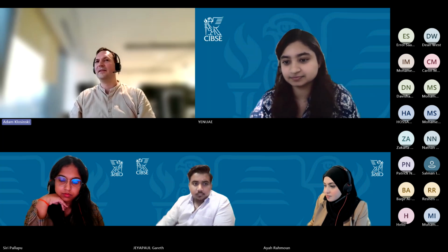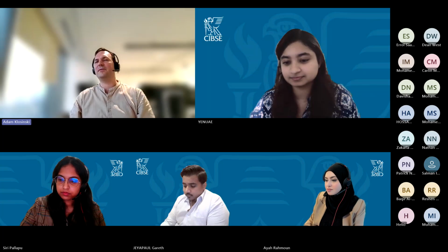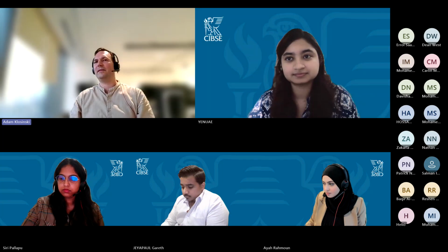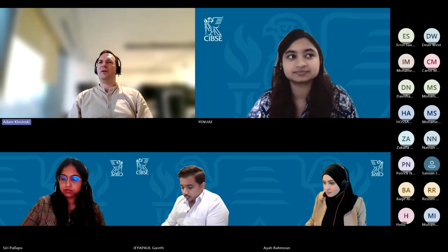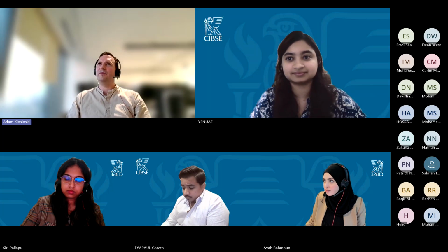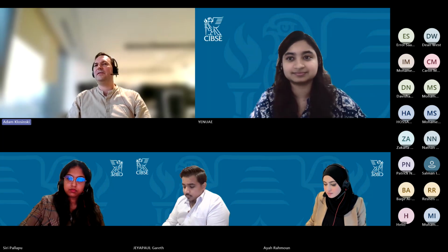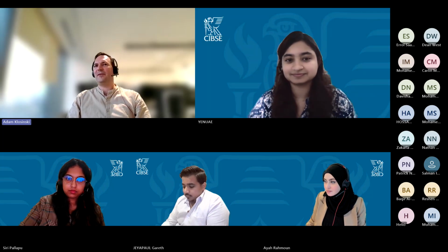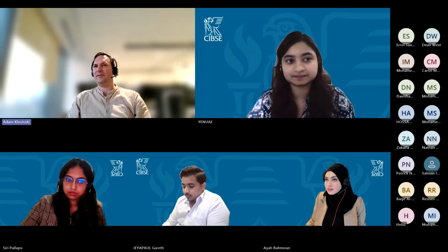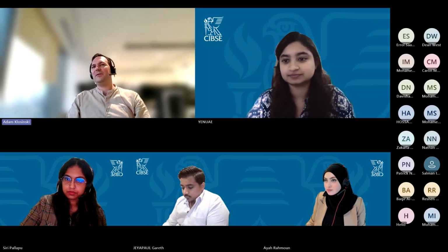One of these is BIM Track, which is also widely used, and it automates the information about what the clashes are, where they are, and who is going to solve them. We need to remember that in the clash detection process, spotting the clash is just the initial phase. Okay, we spot the clash, and we know we've got some problem, but the most crucial part is how this clash would be resolved and who will resolve it. Yes, because there are thousands of clashes.